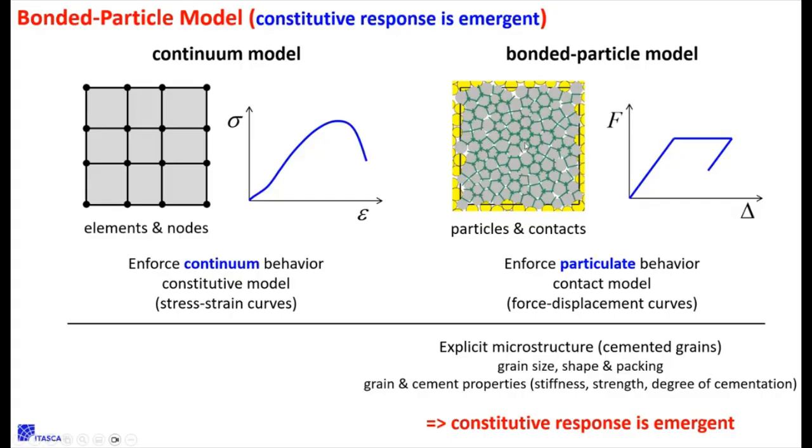And so if you actually build a material at the true grain size, so if we were modeling that granite, this is between like 1 and 4 millimeter diameter grains. So if we just had a 4 millimeter ball, then a beach ball is a grain, right? And if we have a specimen that's 50, it's going to take like 200 of these or something like that. So maybe we could directly model a specimen of rock, but if we wanted to model an entire excavation where the excavation is like 4 meter diameter, we just don't have enough capability to do that.